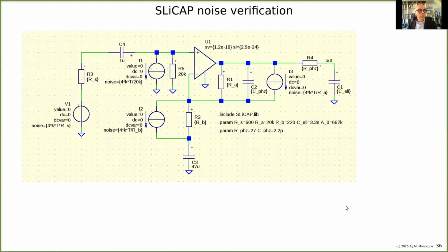We can do all the verification. This is really a horrible task for SLICAP, because here I put capacitors in, and these capacitors are assumed to be shorts for the noise. So by design, I assume that these components do nothing with the noise.